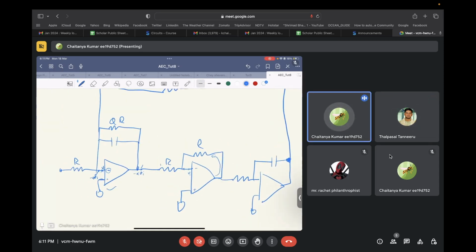we see that if we have Vi over here, we will have some minus alpha Vi at this node, and minus alpha beta times Vi will come at this one. So this loop is also having negative feedback with the signs in this way. You understand? Yes, sir.